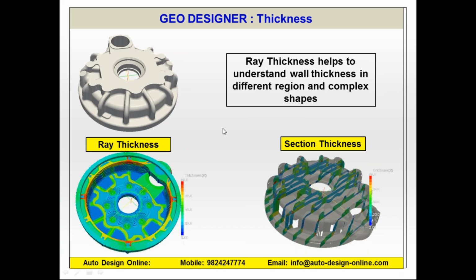Sandeep, you were referring earlier to the thickness of the cut section. What you see here, if this is the same casting part, is that wherever you see the orange or red color, these are exactly the locations where you have higher thickness. And the blue color region is the reason why this software was showing this color: the blue was solidifying first, and the area in orange or red was indicating which will solidify last.